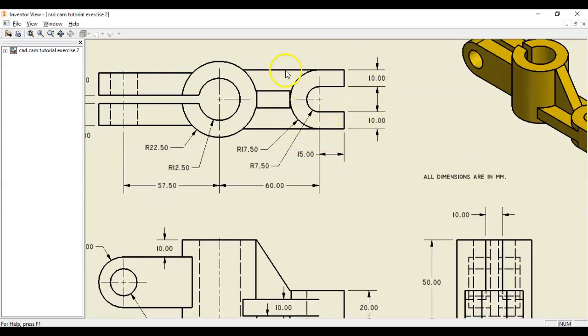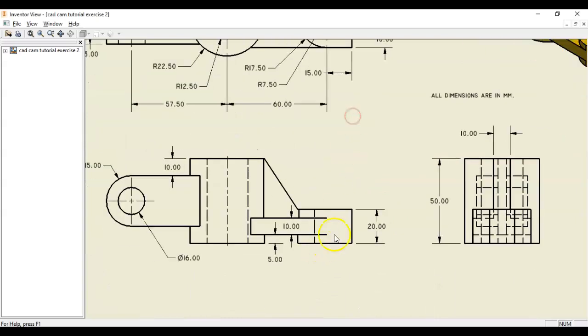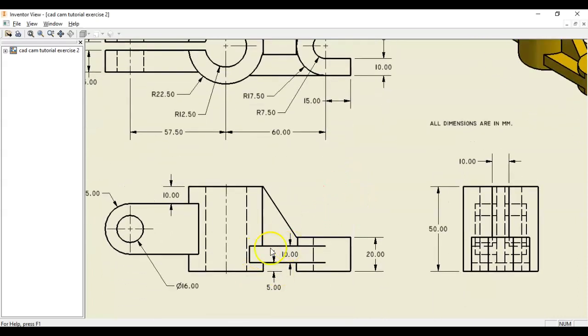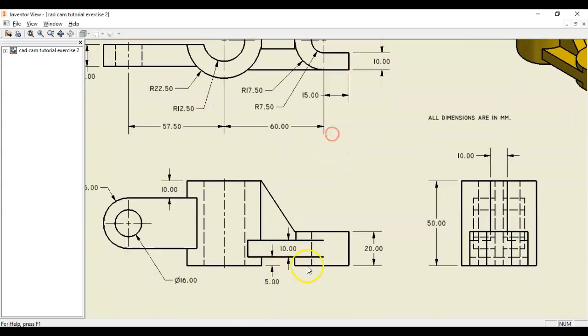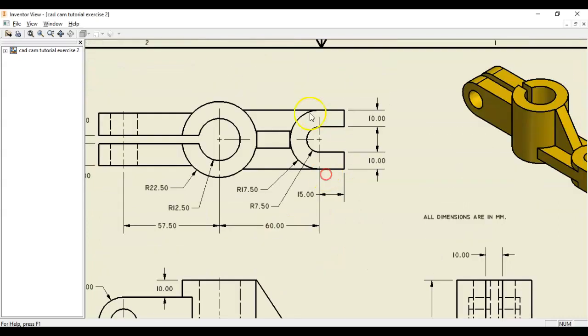So this width right here from here to here is simply going to be the diameter of this arc right here. So we'll double this number. We could also just, since this horseshoe piece is lined up with the bottom, make that first and then make that second, and we'll have a drawing surface and the correct radius. So let's start there.